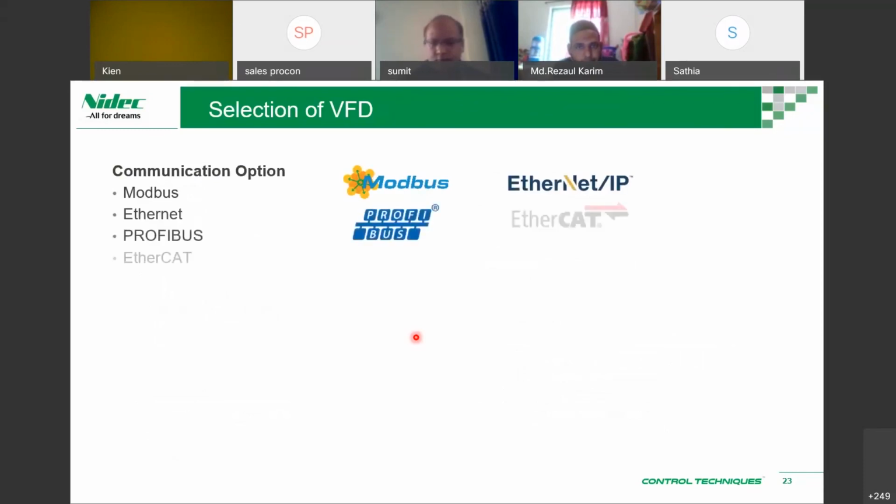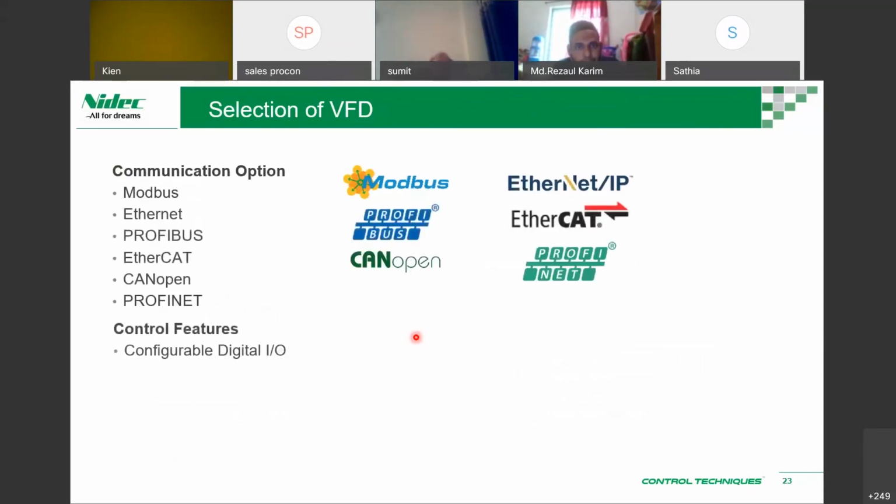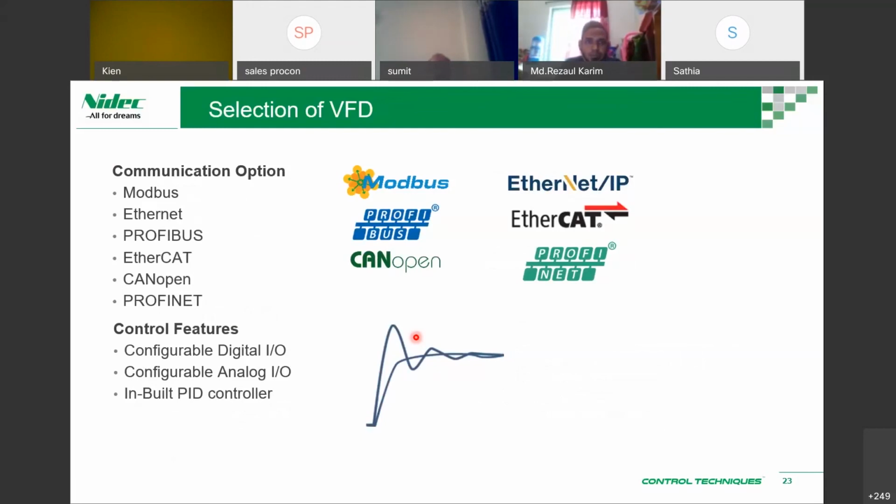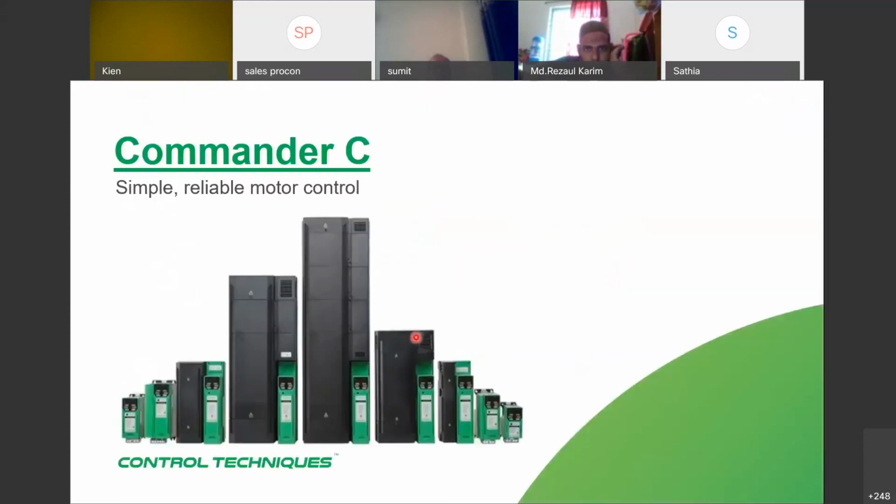And this is important when you're using PLCs, so you're trying to communicate the drive with the PLC. Whether it has configurable digital I/O, whether it has fixed digital I/O, whether you can configure analog inputs to something else. This allows us to really have good control over the VFD, the drive itself, and the onboard PLC. Some of us will be OEMs, and we want to have our own features so that any competitor who tries to replace our drive will not be able to do so. So an onboard PLC would be a perfect fit. It really depends on what you're trying to do.